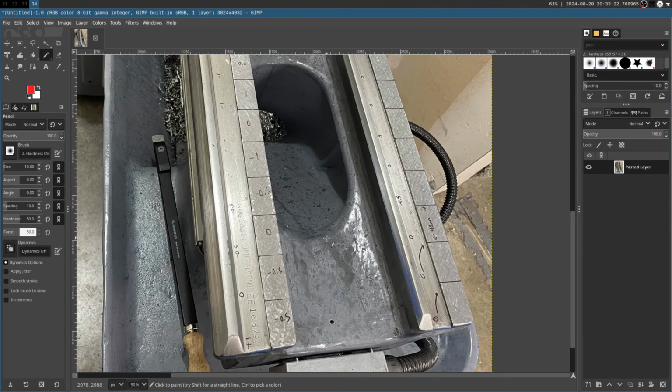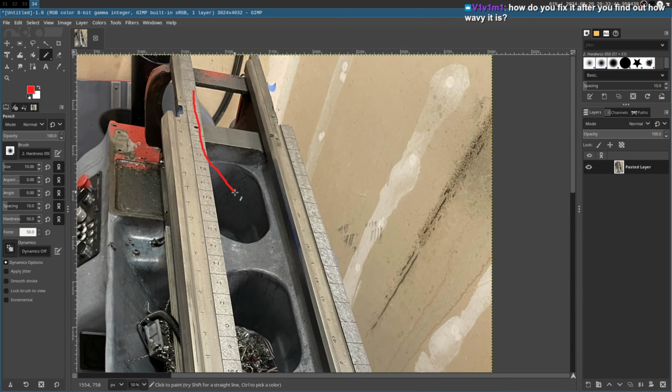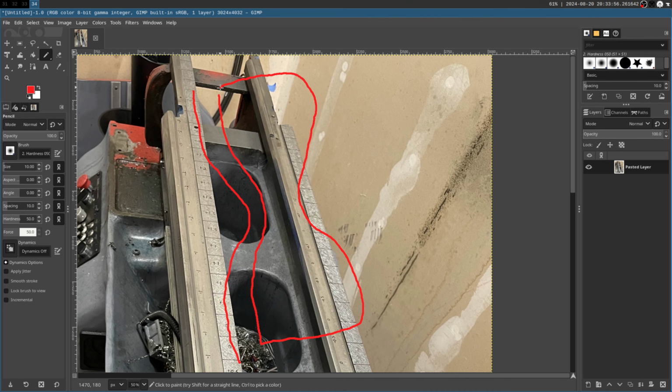So why do you need such high flatness in these rails? These are basically what determines where your tool is, and your tool is digging into your part and cutting the shape into the part, right? So effectively, if I were to have a bump on this surface like that, and I were making a long cylinder, that long cylinder would then have an hourglass shape, right?